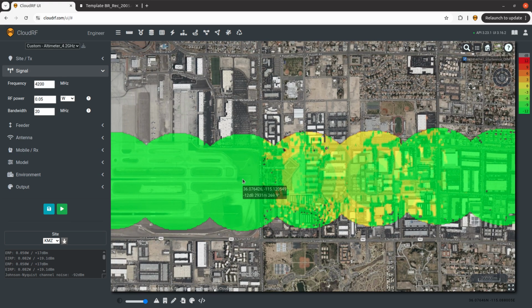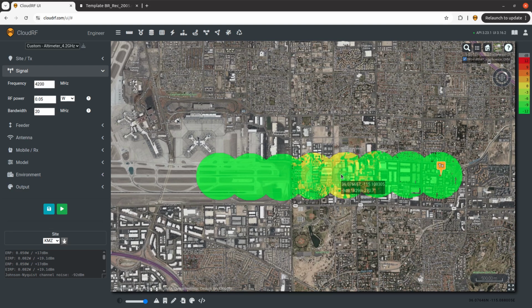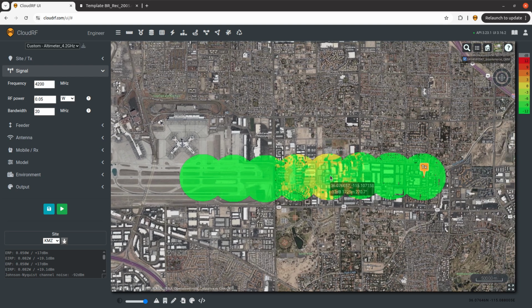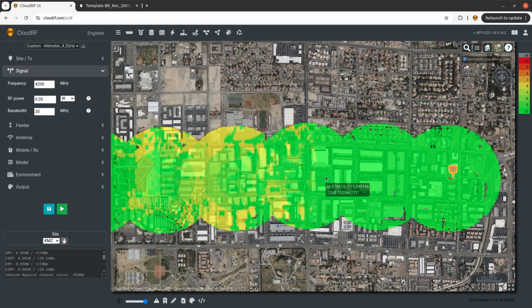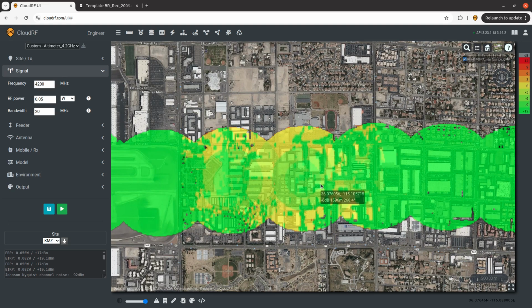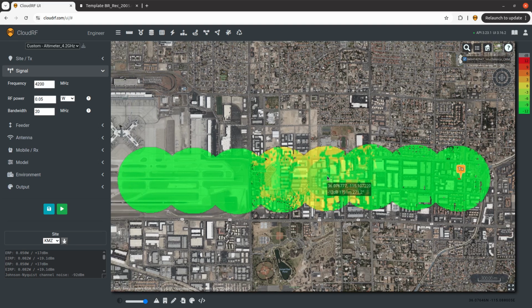So why do they tell you to switch your phone off? Well, a modern 5G cell uses beam steering. It's not just the same power in all directions, it flexes the power to meet demand. If several hundred handsets all of a sudden appear in the same location demanding service, a beam will likely get steered towards the plane. It won't get steered up because they have tilt limits on these, because you shouldn't be serving handsets in the sky for all sorts of technical and commercial reasons. So the risk is very low.